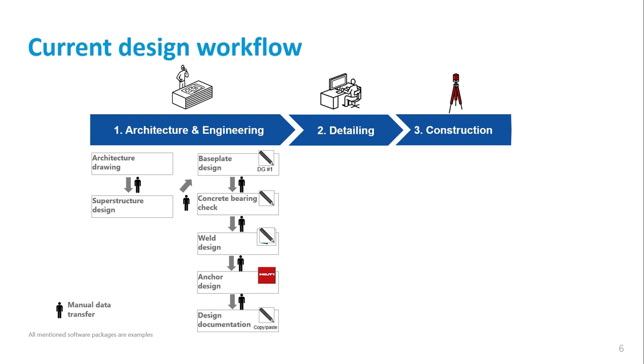Once you did the base plate design, you probably start with the anchor design. You might find out that there is no solution. Then you need to go back to the base plate design and probably size your base plate differently. So there are a lot of manual steps and a lot of iterations needed.